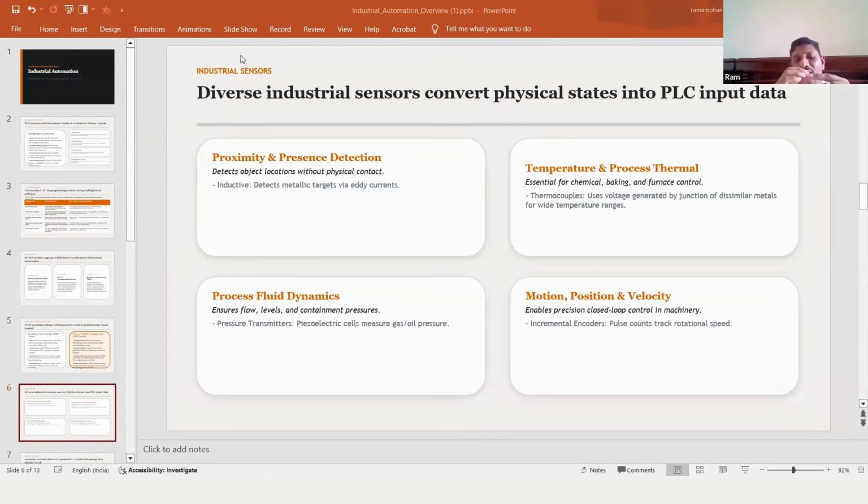Whatever the distance between this obstruction and the sensor, we can program that and define it. If it is very nearby, if it is 10 centimeters, then it should give a longer beep. And if it is 30 centimeters, we can call it a warning signal. And if it is beyond that, it can ignore. So this is the ultrasonic sensor that is being used in cars. Whenever it reaches any obstacle, it gives a signal, and thus smart cars will stop automatically. So these are two examples of sensors.